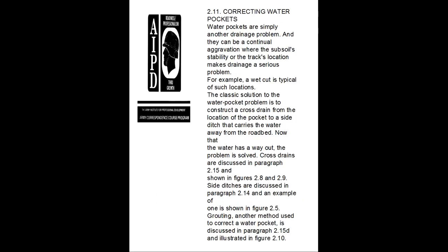4. Freezing weather. If water pockets are allowed to remain until winter, the freezing temperatures cause ice to form in the pockets. As the ice expands, the roadbed heaves and soon appears uneven. The track can be leveled only by adding shims, bearing pieces of used rails, to the low spots. Since shims are placed either between a tie and a tie plate or between the tie plate and the rail, draining the water pockets has to wait until the spring thaw. The amount of labor and material needed at this stage is much greater than that required earlier to eliminate water pockets. 2.1.1 Correction of water pockets.